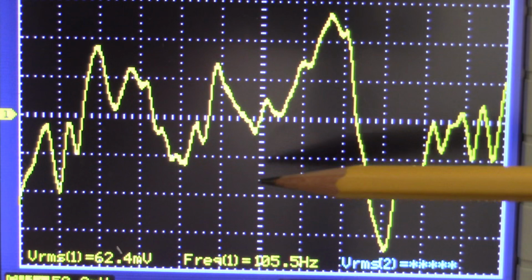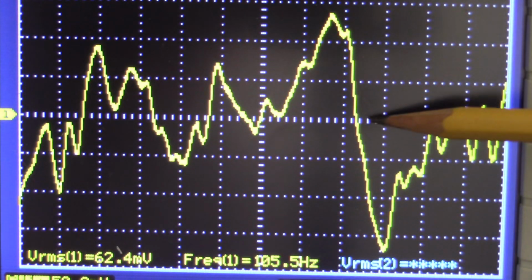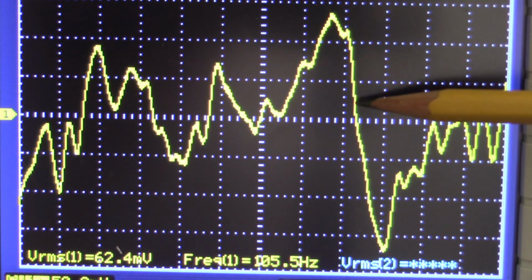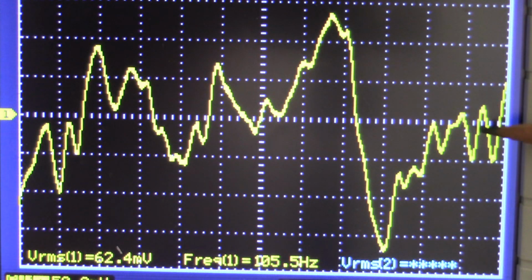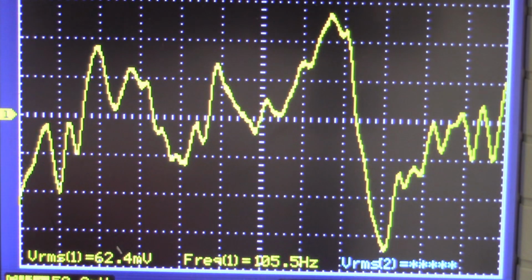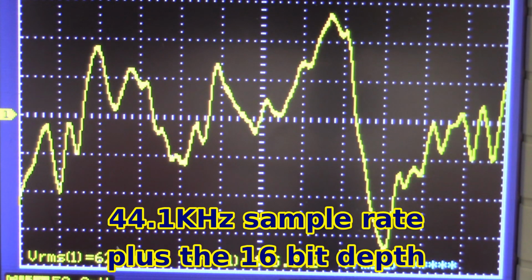This is like 320 by 240 or something like that on my old oscilloscope, and it doesn't have a lot of resolution, so that's why you see the stair-stepping look when you look at the waveform close. I'm not going to get into it in this video, but if you understand the Nyquist-Shannon theorem, you understand that an analog waveform can be perfectly represented with a proper sample rate, which, for the audio spectrum, 44.1 kilohertz is plenty adequate for.